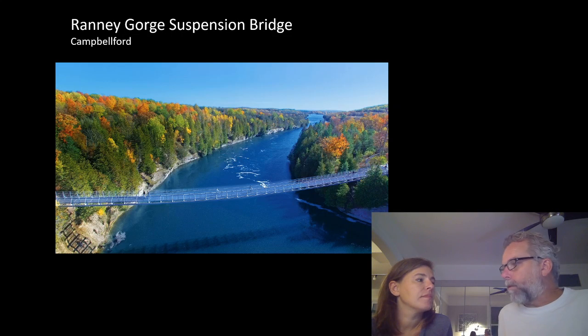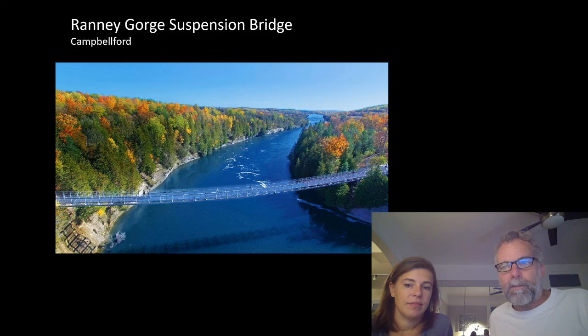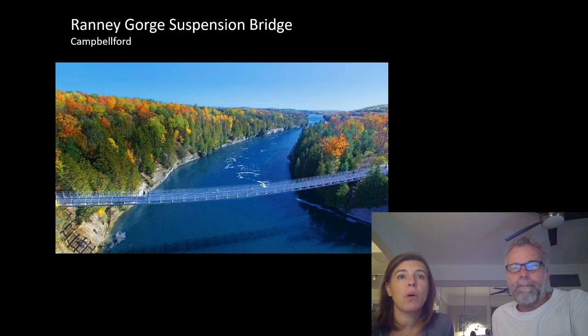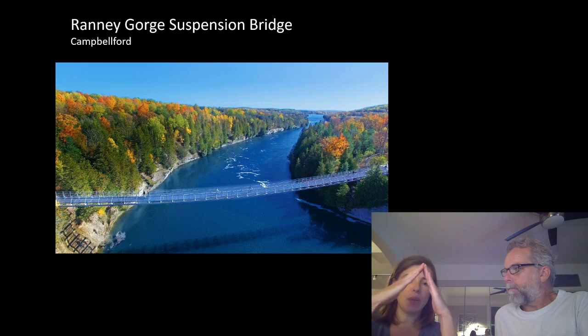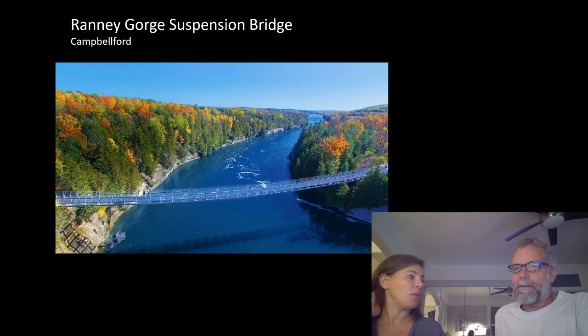If you're in a soil situation or weathered rock, there are lots of situations where those forces are just unmanageable, and you'd have to cast massive amounts of concrete, which you see happen for suspension bridges, for major waterways with vehicles going over it all the time. Kind of at the midpoint ones, they balance each other out by having the other cable on the other side, but eventually at the very ends you have big, massive abutments.